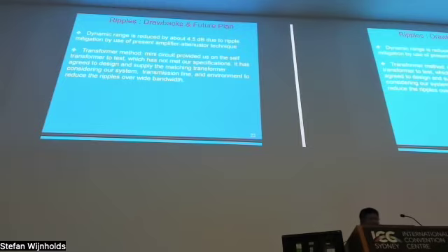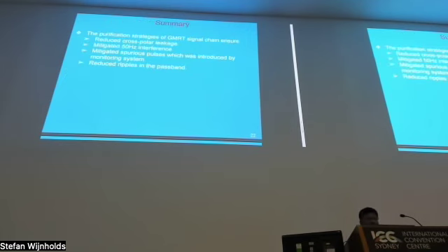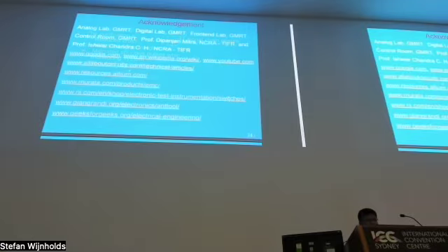So we have asked them to give a better matching transformer which will meet our requirements and give better ripple reduction. So the summary is we have been able to reduce the cross polar leakage, mitigate the 50 Hz interference and spurious pulses, and reduce the ripples in the passband.